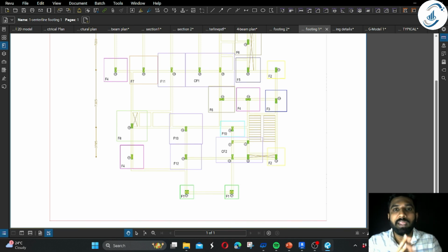There are chances that when we are only referring to the 2D drawings, the electrical lines or any other service that is running underground may pass through the foundation. And foundation being a very critical part of the structure, usually we don't pass any services through the foundation. So this error is usually spotted when we are executing these 2D drawings onto the site. So what do